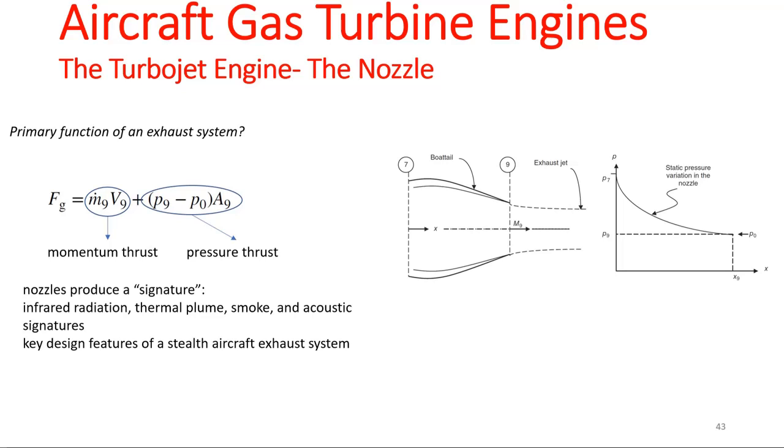Okay, so essentially because of those adverse pressure gradients, we have to be mindful of the viscous losses, right? What can you say about the nozzle? Flow separation is not as important because it is very unlikely to happen, right? And if it happens, it's not going to have that much effect, for whatever reason. So in nozzles, we have favorable pressure gradients, compared to the adverse pressure gradients we have in a diffuser.